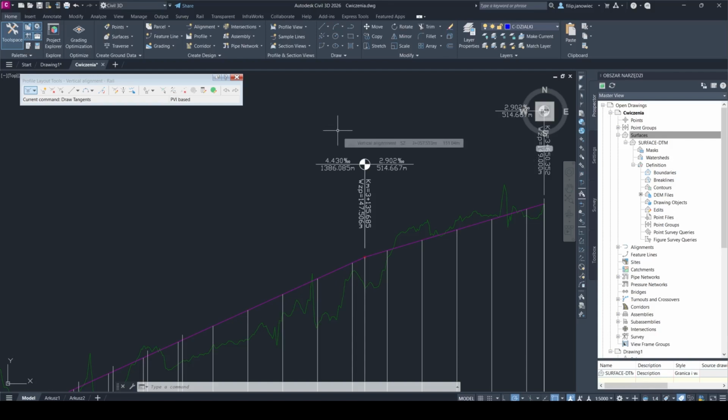The routes where the vertical curves must be designed are the places where two straight lines meet, where the difference between the two nearest gradients is below 1 promille, in some events 2 promille.